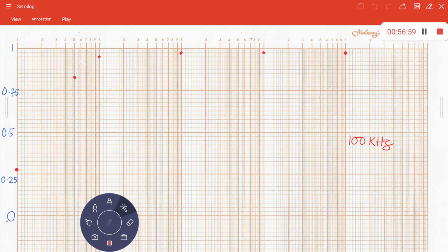Okay. So now the low frequency operation, the low frequency region. You require this graph. Using this graph, you can draw this low frequency part. I've got how many? 1, 2, 3, 4, 5, 6 points. You already got them. Now join them freehand, just like this. Done? The low frequency part is half done.